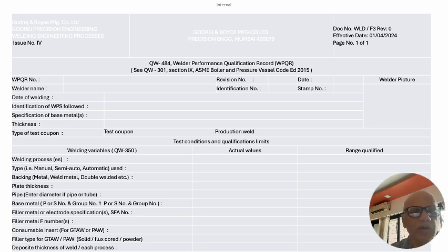it also, to an extent, gives a confidence about meeting the non-destructive test results. These both are very critical and important for any part or equipment. So the first step is always to prove that the parameters we are choosing, the consumables we are choosing, and other parameters like edge preparation, pre-heat, and post-heat, if there is any heat treatment, and subsequent to that, whatever is the intended use of this particular weld, does it meet the designer's expectations? So that is proved in the PQR.